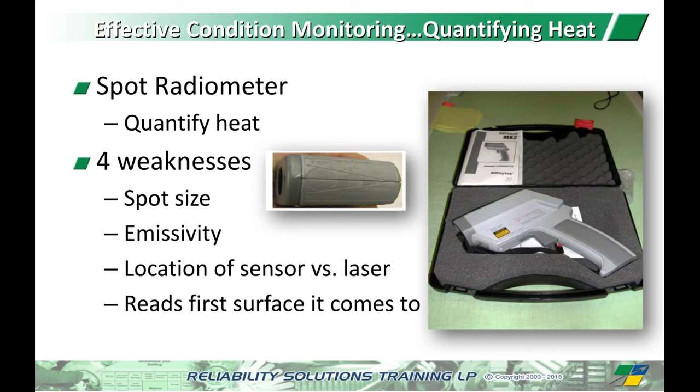it's overheating? And the first reaction to that is to try to add another cooler to it, or put a hose on it to try to cool the reservoir, or a variety of other different things. And we never ever go back and ask ourselves, why do we have the heat in the first place? If the system is properly designed, and to be fair, most of them are, and we're operating it within its design specs, then the normal temperature for a hydraulic system reservoir should be 80 to 150, maybe 130 is optimal. Don't want it too low, we don't want it too high.